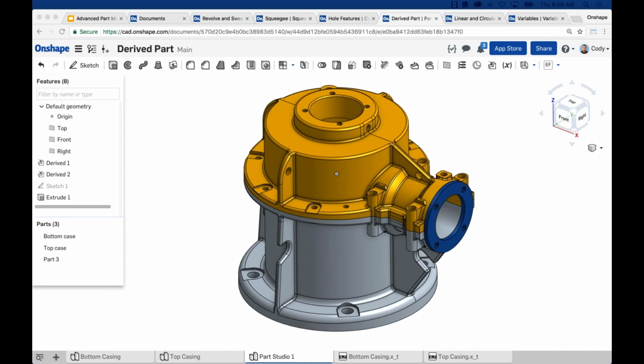How did you get those casings to align correctly? That's the same question from earlier. They were modeled that way. If your parts are modeled in the correct orientation, they come in the same orientation they were modeled. Oftentimes, though, that could be arbitrary. And in that situation, you need to use a transform.